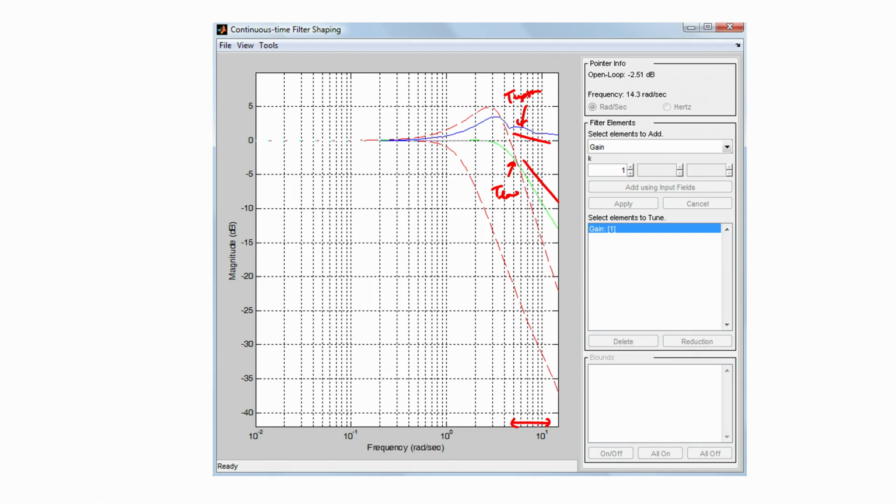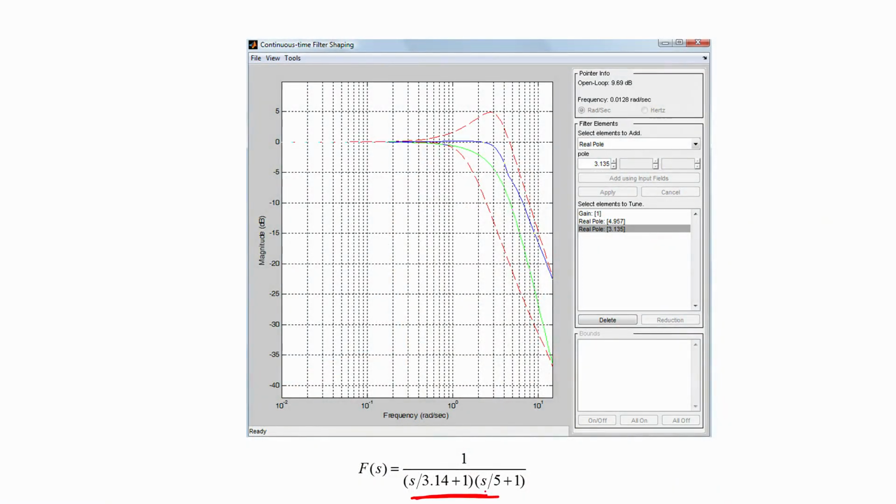So once again this dialog box allows us to pick the pre-filter structure that makes sure that the transmission functions T upper and T lower are within the specified bounds. So we can choose the pre-filter to have certain gains and certain pole locations and certain zero locations that together make sure that this T upper and T lower are within the specified bounds, and I have used this software to determine the structure of the pre-filter, and the pre-filter structure is shown here.